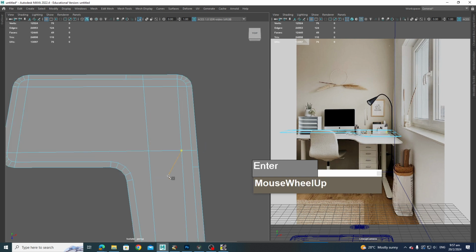Okay, we fixed the area here now. Now let's take a look at this area here. So we want to maybe cut across here to here. Press enter. And then maybe from here to here. So we created our four-sided faces just like that.